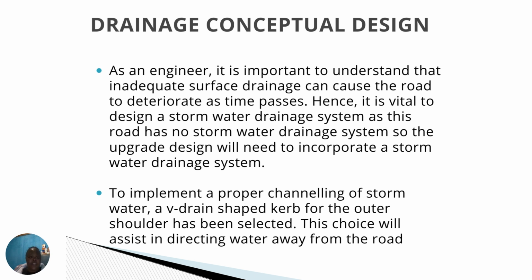Now moving to the next slide, the drainage conceptual design. As an engineer, it is important to understand that inadequate surface drainage can cause the road to deteriorate as time goes on. Hence, it is important to design a stormwater drainage system, as this road has no stormwater drainage systems. So the upgrade design will need to incorporate a stormwater drainage system.